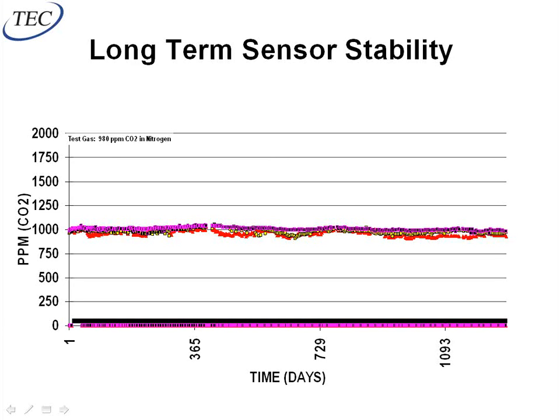I'm not going to say, oh, my normal job said I had to have 30% outside air, so I'm going to modulate it from 30 to 100% damper position. No, I'm not going to do that. I'm going to modulate it from 30% down. So 30% is where I'm going to be at if I need to bring in more air for CO2 control.